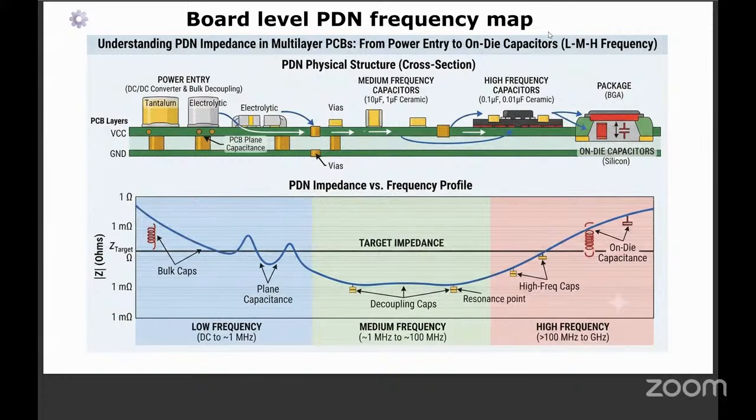At a gigahertz range, even the VCC and ground planes, which are parallel and very tightly spaced, give much of the capacitance required. We have shown this: if we don't meet this frequency, the capacitors will act like an inductor. They are no more capacitors, they are inductors. So that's why they distribute the capacitor values. I have shown a graph at the bottom.